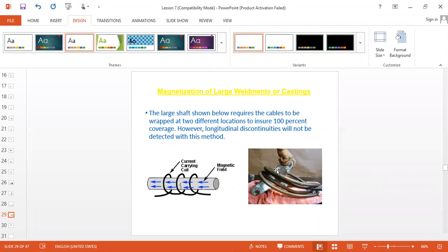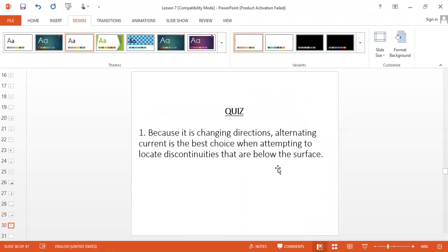In this particular area we can't see the defect because the particles will not enter there, as the part is close to the coil. Otherwise we maintain some distance between coil and job, then we can detect all discontinuities over the entire surface.